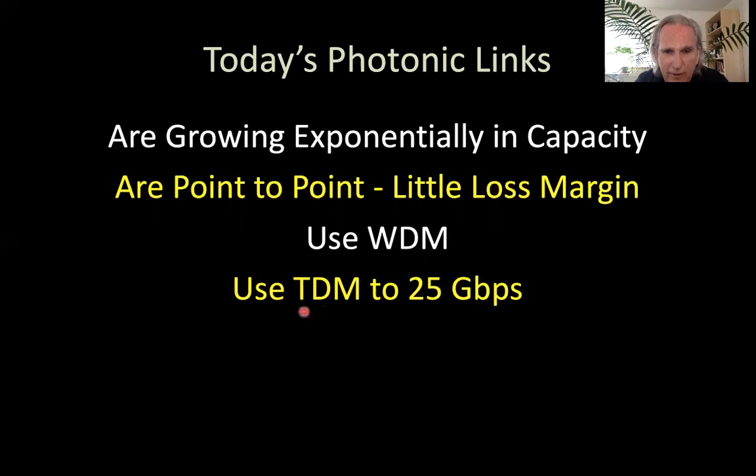The other thing that I didn't really mention, but is a fact, is time division multiplexing. We put together many telephone conversations that may be 64 kilobits per conversation, and then we time division multiplex them, and we stop at 25 gigabits per second. Past this, we start running into the dispersion limit. Below this, we're limited by the loss budget. The loss budget, if we go faster, gets even smaller. With silicon photonics, we can push this to 50 and still be loss limited.